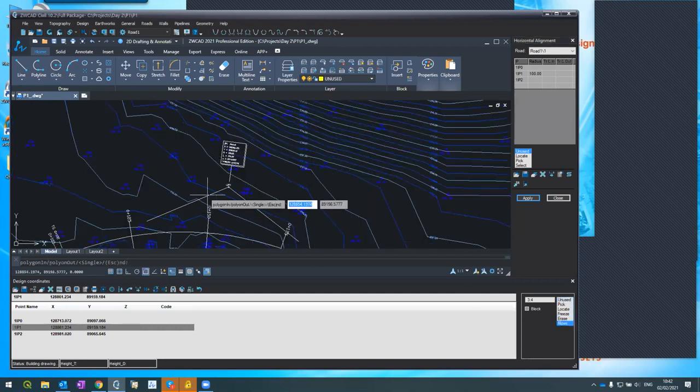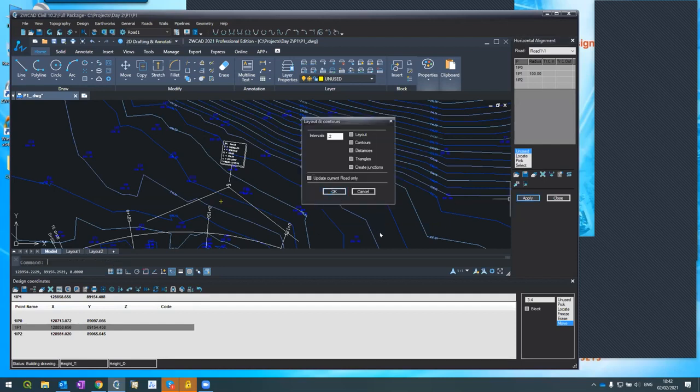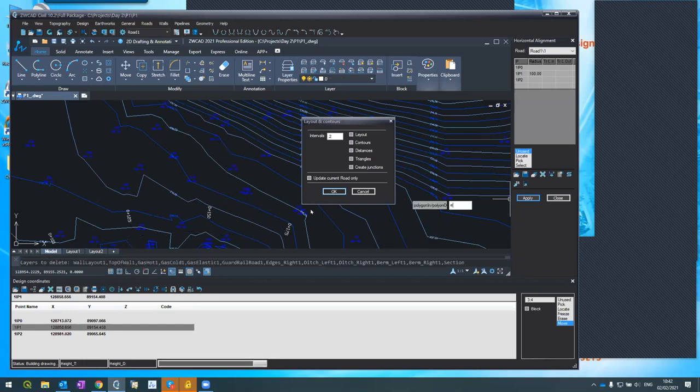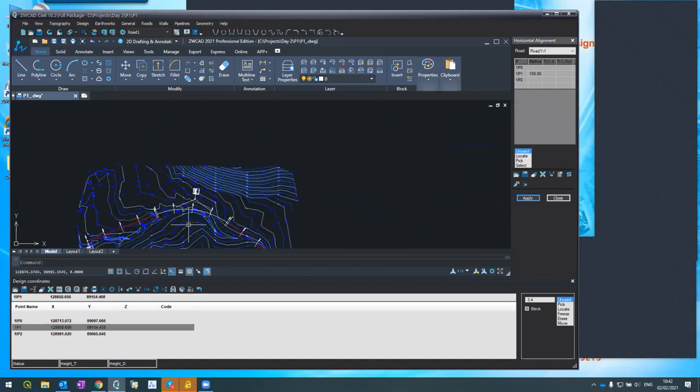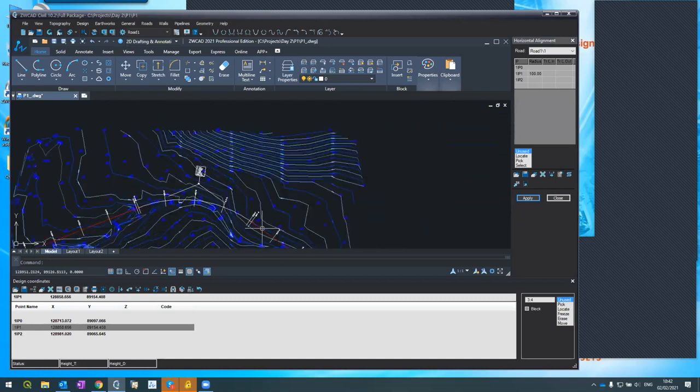Move, select, from here to anywhere, here. I press apply on the right and okay. I don't need to do refresh. When I apply, it will do refresh by itself. And then the road changes accordingly. I hope this is clear. You have to practice if you want to better get a hold of it.